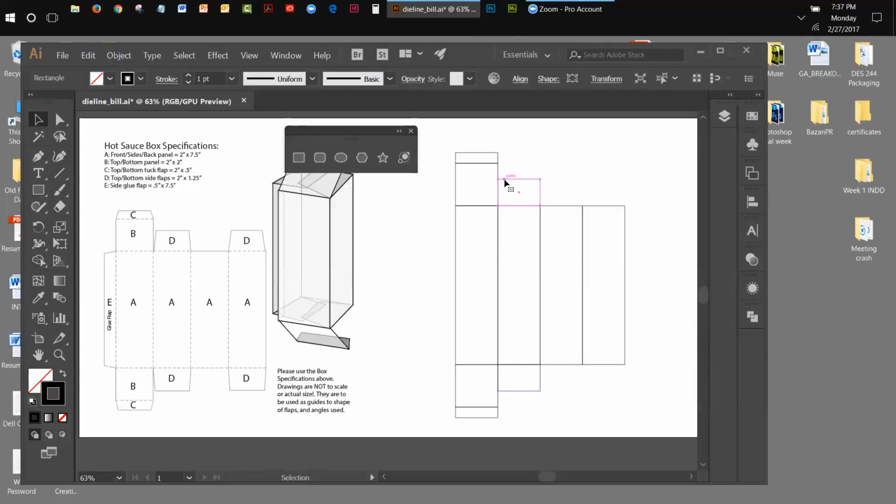And then I'm going to select both of these guys, again, trying to do this as quick as I can. By selecting both of them, I hold the Shift key down. You guys know that, right? Yep. Okay, so I'm selecting more than one. I'm using the Shift key. And I'm going to hold down the Alt key, and I'm going to carefully drag these guys over until it aligns at the end like that. And now I have all the pieces done except for my glue flap.